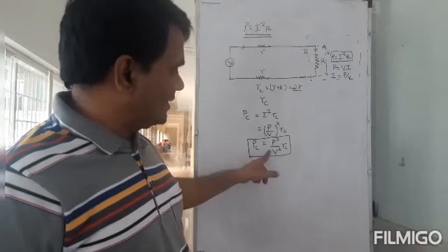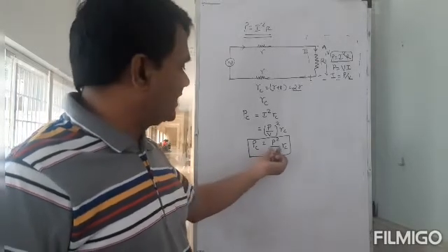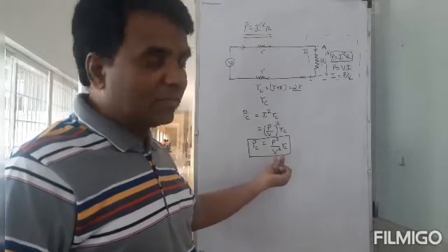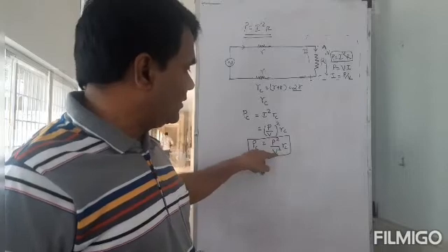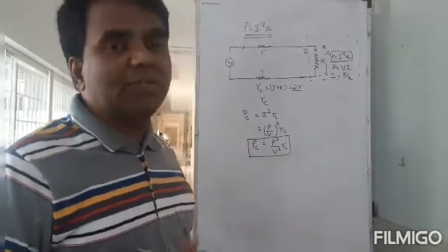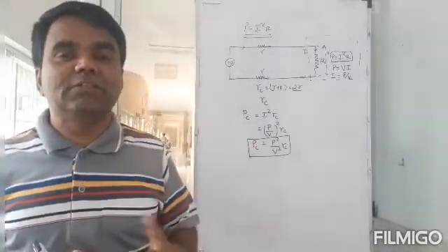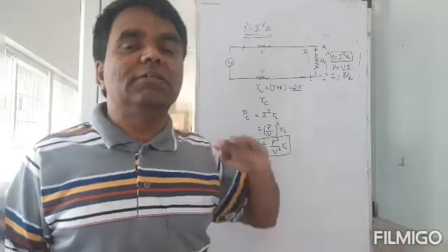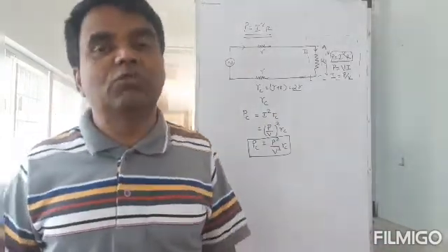But notice here, suppose if your appliance works at a higher voltage, if you can increase V, okay, then this denominator becomes a bigger number and PC will become a smaller number. So it always pays to transmit power at a very high voltage than a low voltage.